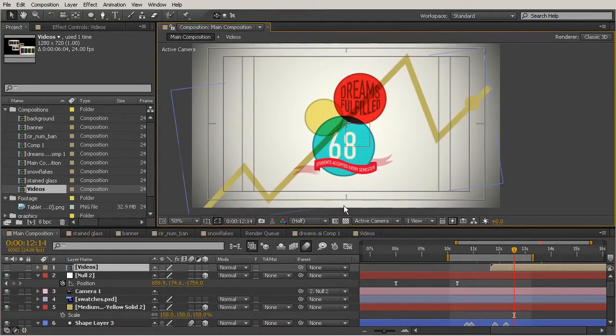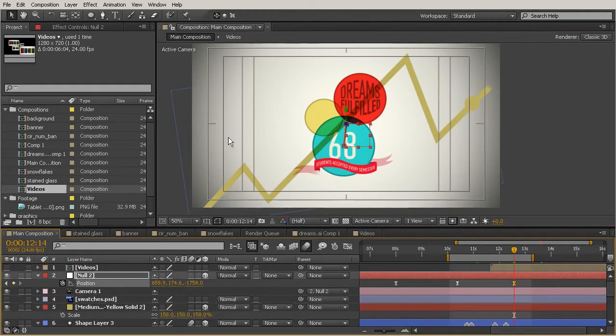So I'm going to go ahead and add another keyframe here so that it's telling my camera that this whole time I wanted it to stay in the same position so we can finish watching this animation. And then over about the next 12 frames, we'll go ahead and pan our camera up in the direction that our graph is moving. So let's move forward 12 frames by holding Shift and hit the Page Down key one time. And then we'll hit Page Down 2 more times to bring us forward those 2 extra frames.